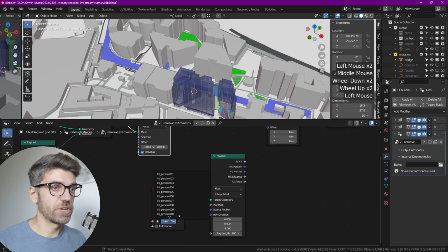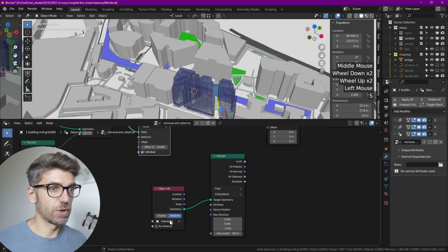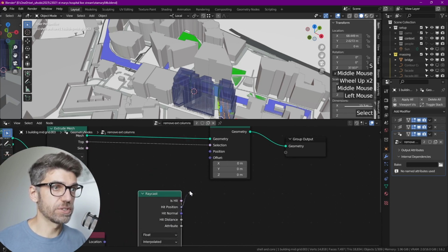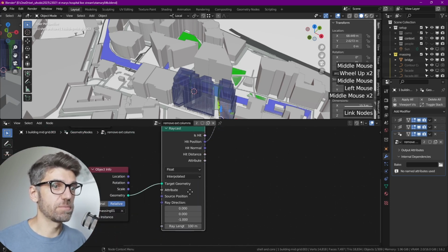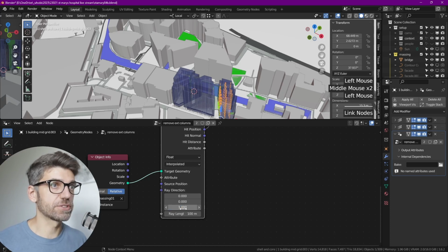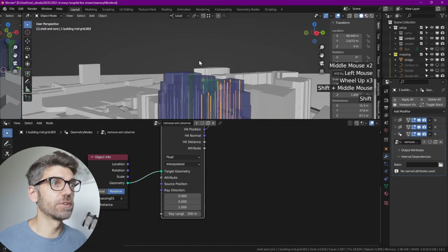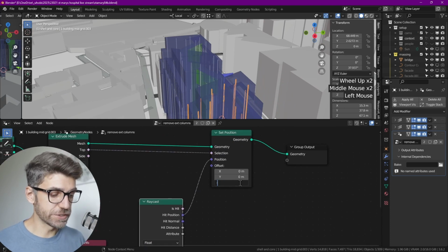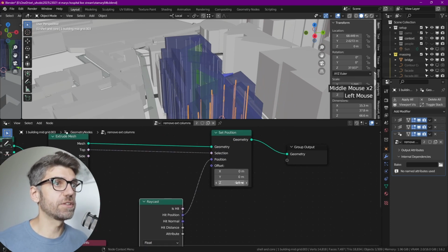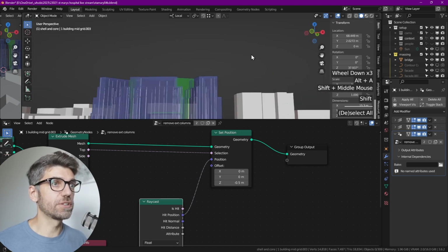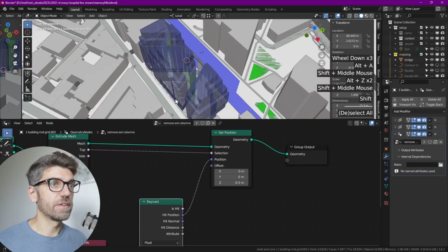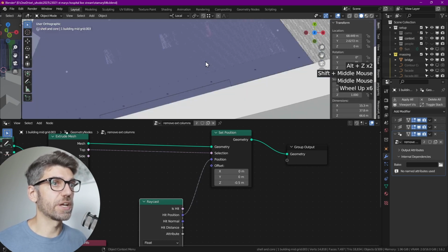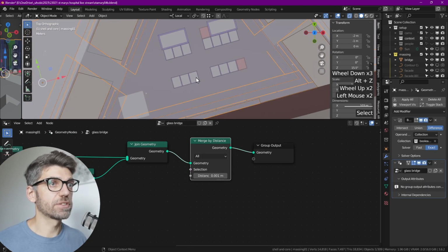So now let's change this to massing 01. Relative distance, that's correct, and hit position is the bit that we want to change, and make sure this is going in the positive direction instead of the negative. And now all of these columns should be reaching to the top. And let's do a slight offset down, minus 0.5 meters, so it doesn't go completely to the top. Great. Grid is done.